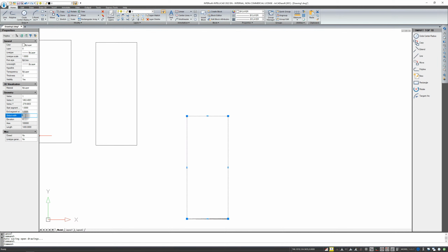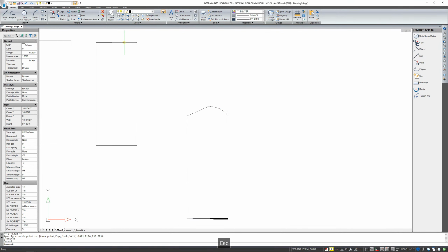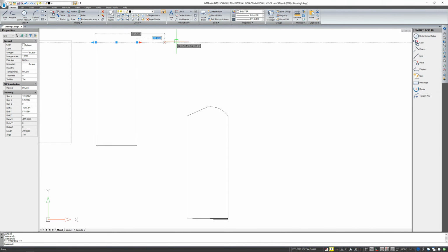A polyline also gives you possibilities for additional distortion. You can lengthen such a rectangle, you can add a vertex, then you will change it to a polygon. You can also, as you may have noticed, change it to an arc. So depending on what you need, the polyline can be further modified. Lines do not have such additional points. You have the possibility only to shorten it, lengthen it, and change the position of the starting and ending points.